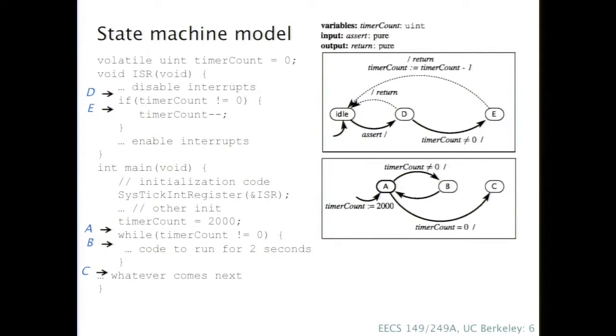But you could have a state machine that's incomplete in the sense that you could be in a state and there's no enabled transition out of it, and we implicitly assume there's a self loop that is taken if no other transition is enabled. So the question is, can we discard B? Would it still be faithful? Oh, the timer count not equal to 0, loop to A, and get rid of B altogether. Yes.